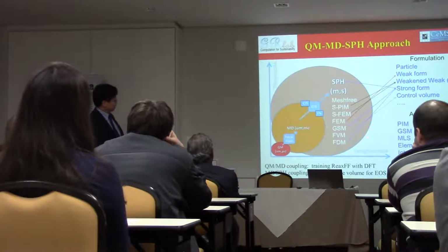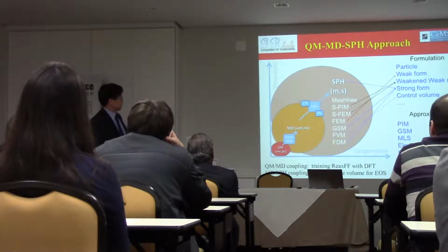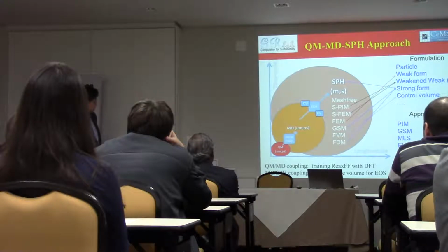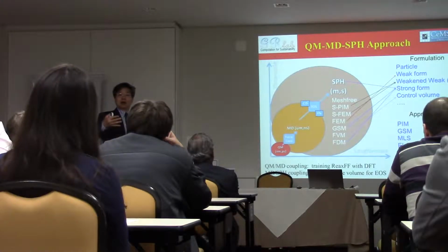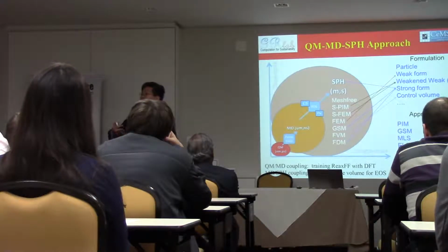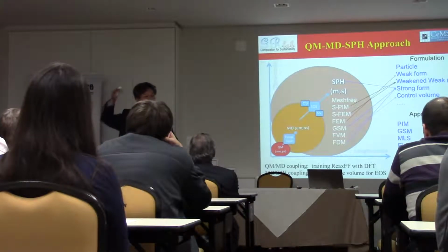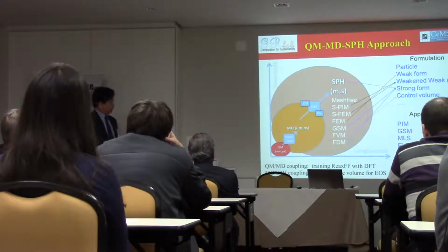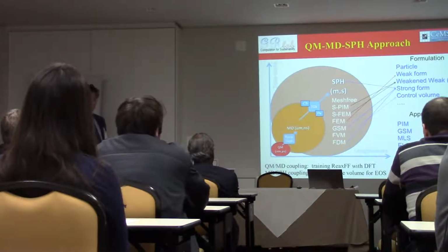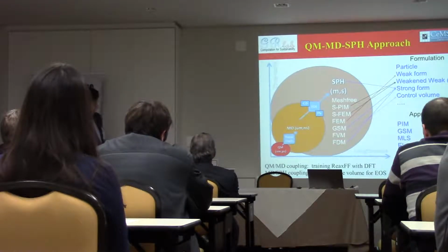So that is why for CFD problems, people often use a finite volume technique. Now, this is only talking about the finite volume technique. They use so-called control volumes. So you bring in the so-called physical law of conservation. When you cut the domain into pieces, you're making sure the conservation is always maintained in your discretized model. With this kind of idea, you can formulate all sorts of numerical techniques.